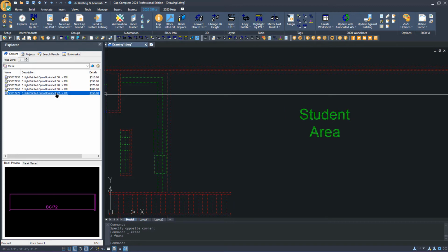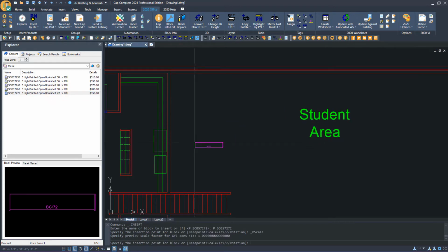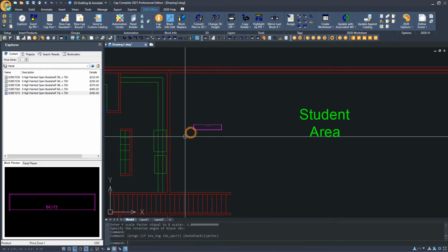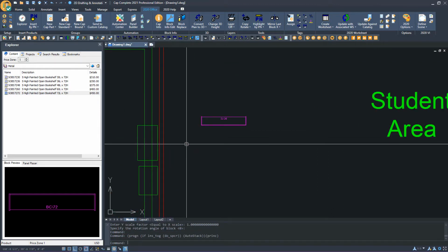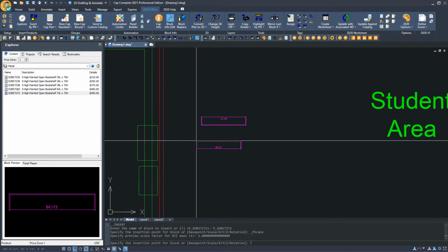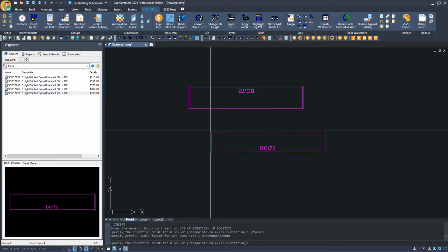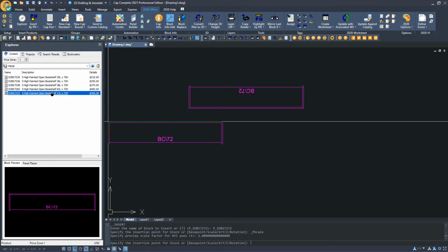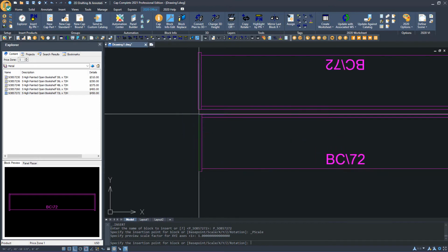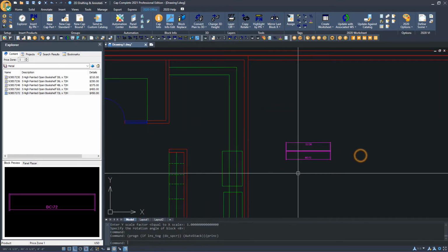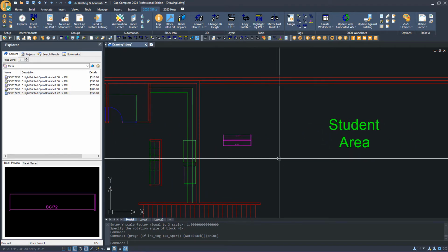And so I'm going to go ahead and just drag and drop this bookcase in and place it by just left clicking and rotating that in place. And now a really quick feature is I can hit my space bar, and because we have what's called running commands, that bookcase once again appears on my cursor. I don't need to come over and drag and drop that back in. And so I can come over here and snap to the node, rotate, and place those bookcases back to back.